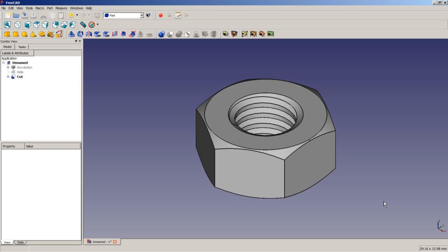A second trick would be to use part primitives instead of revolved or extruded profiles, at least with earlier versions of FreeCAD. I was thinking that FreeCAD, or at least the geometric kernel, was reacting more robustly when doing Boolean operations with primitives rather than revolved or extruded profiles.